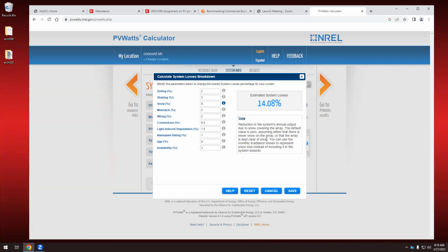I recommend that. So when it's snowing and the snow stops, someone from maintenance should go and get rid of the snow. If it doesn't happen and the snow is there for 1 month, is it worth having a PV array? No, it's not. So can we have a system to melt the snow? We can, but again, it will be more expensive. But they have considered that they have 0% of losses from snow.